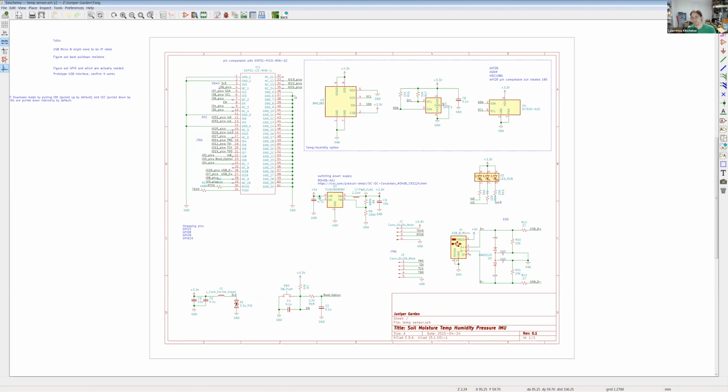There are only a couple of interesting things about the design. It's a pretty basic design. There's not a lot special about it. It basically uses an ESP32-C3 Mini or ESP32 Pico Mini. The only interesting thing about the C3 is that it's actually a RISC-V processor.